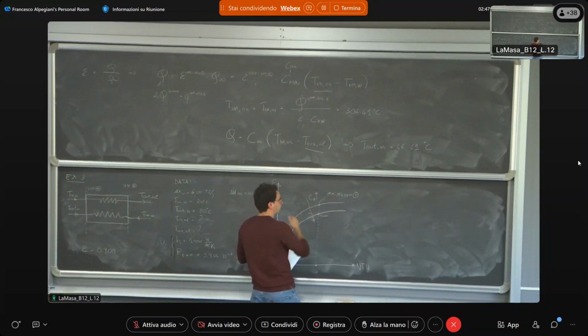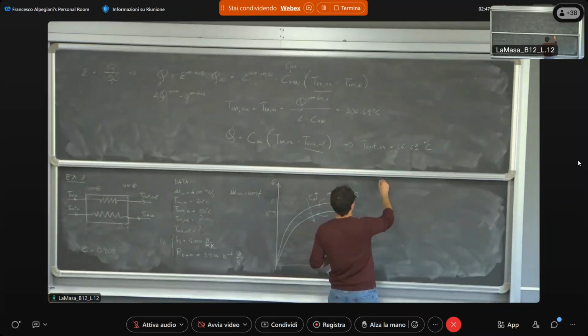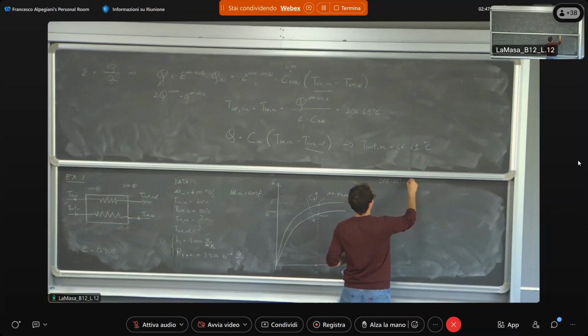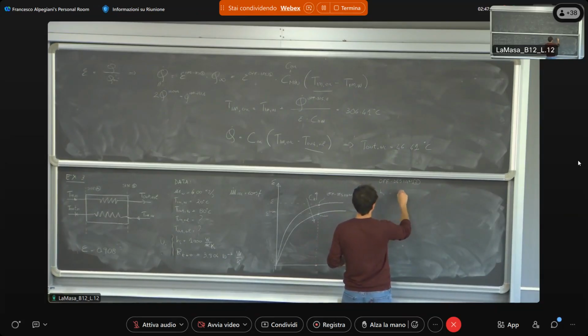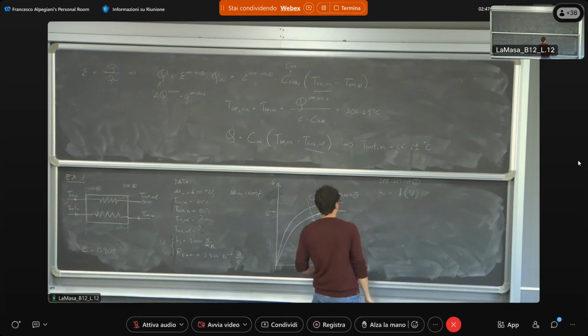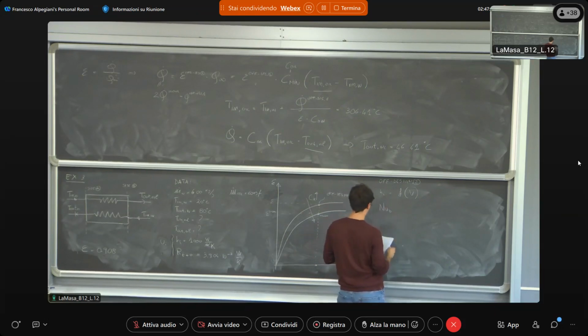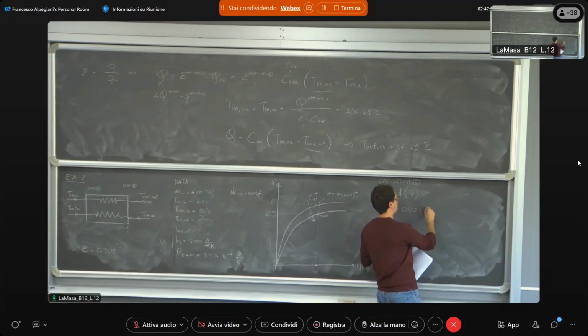So now we are facing the off-design condition, say 2, and so h_i changes with the velocity, so it's a function of the velocity. The Dittus-Boelter equation given in the text is Nusselt, referred to the internal diameter of the tubes, equal to 0.023 times the Reynolds number.